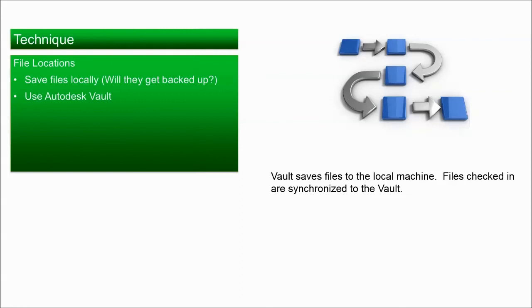File locations. Talked about this briefly. Save files locally. You're going to get a performance boost, but depending on how your company is organized, it's generally frowned upon to copy a file from your server, work on it locally, and then copy it back. I mean, what happens if somebody else opens the file? Well, now you're going to have trouble.